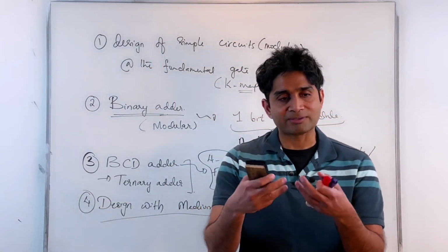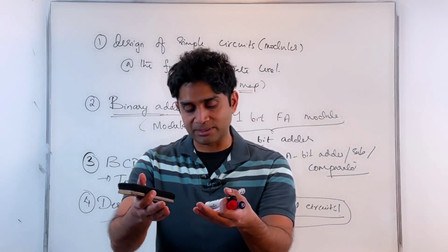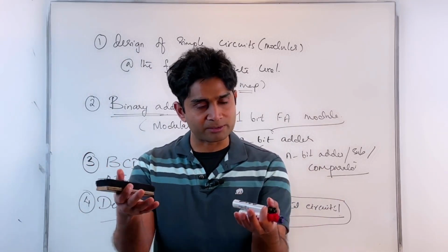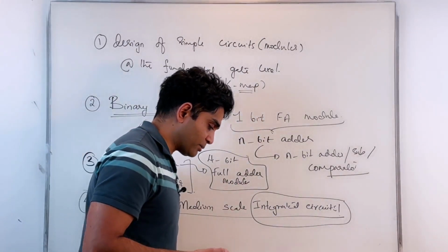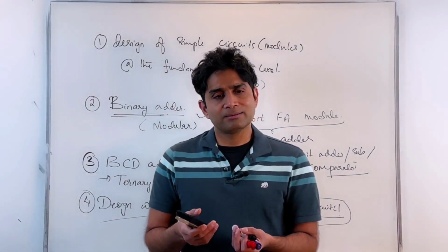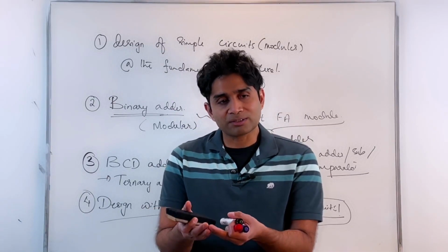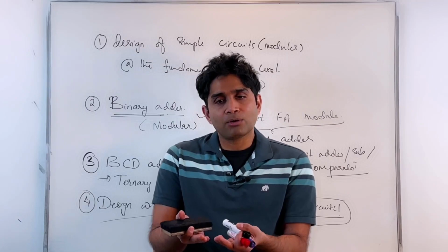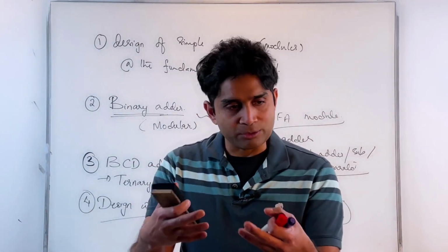Okay, now, for example, your microprocessor, that's a planar technology that's basically done over an entire wafer, a large silicon wafer, like a single crystal silicon wafer, which you will learn more about in your subsequent classes. Okay, and so you're packing millions or billions of these transistors on the same chip, on this microprocessor, and you're building up layer by layer, making your entire circuit.